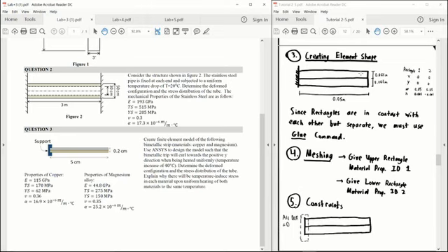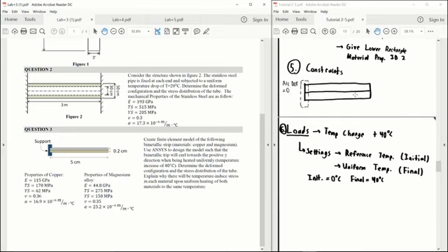And under meshing is where we'd actually enter in which plate has which property ID. So the way it will end up working out is this top plate here will end up having the material ID number 1, and this bottom plate here will have material ID number 2.